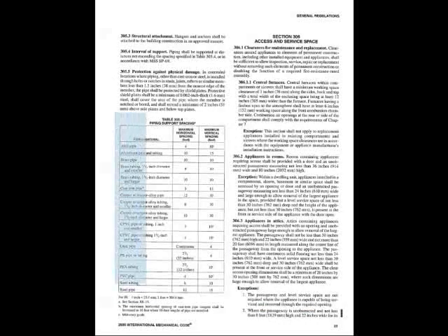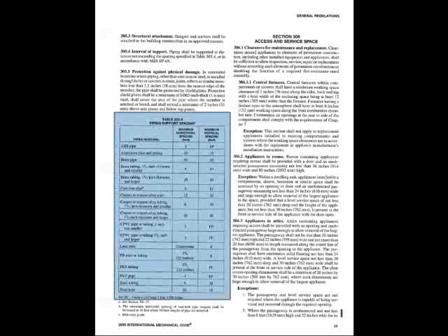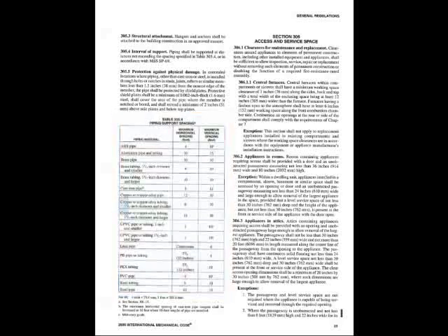Table 305.4 is a table you will need to refer to both in the field and when you're taking your licensing exams. Very specifically, you need to understand the difference between copper alloy tubing, copper alloy pipe, and the different sizes of tubing and pipe. They have different code requirements. Horizontal spacing is, for example, when the tubing is running across the top of the basement ceiling. Vertical spacing is when you're running between floors.